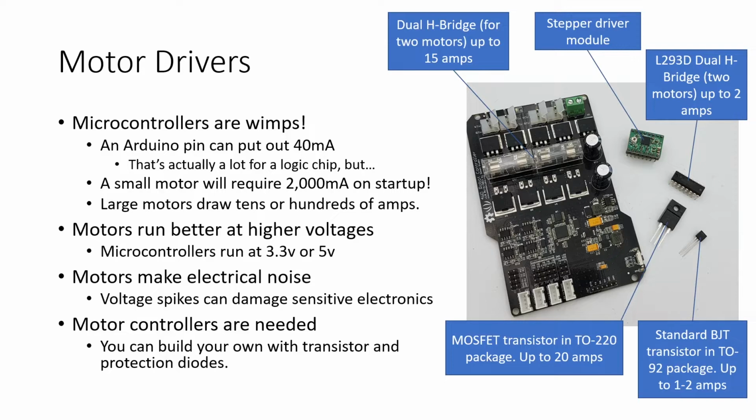This one, actually, if you look closely at the number on it, is an SN754110, I believe. It's an L293D clone. We've also got, for our stepper motors, modules like this. There's a number of different stepper module choices depending on the size and power needs of your stepper motor. And this little surface mount chip right here is actually the brains of the entire operation.